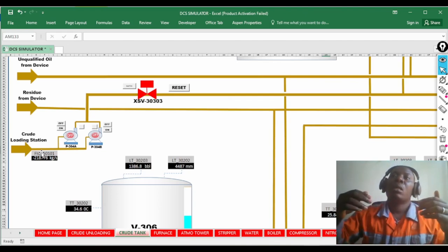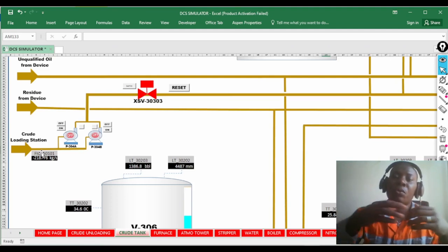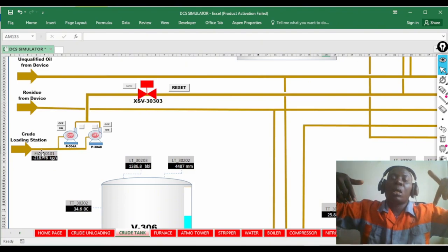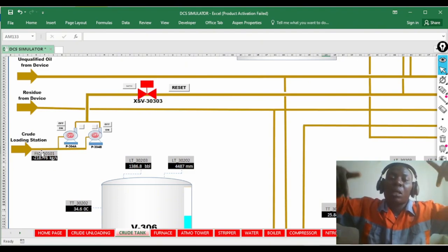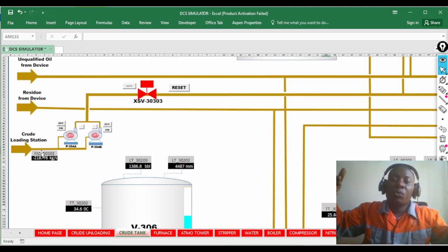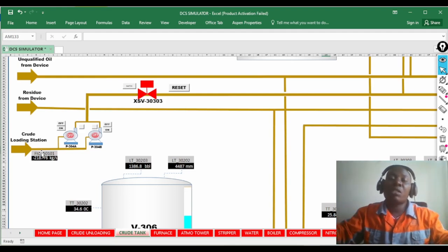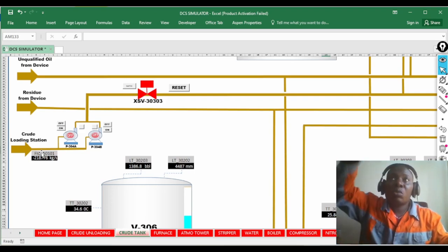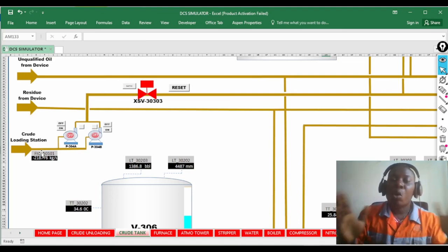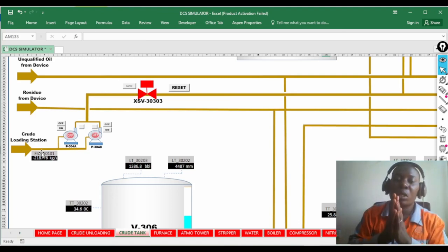And then what if we include a pressure differential situation that can check the pressure before the strainer and after the strainer, and then have a trip due to the pressure on both sides of the strainer?